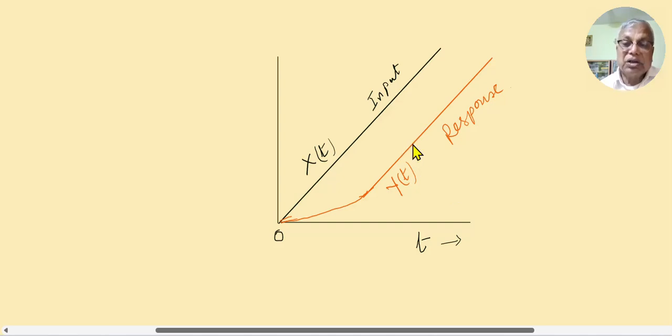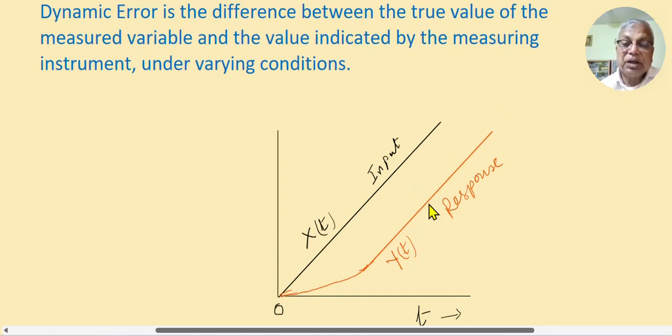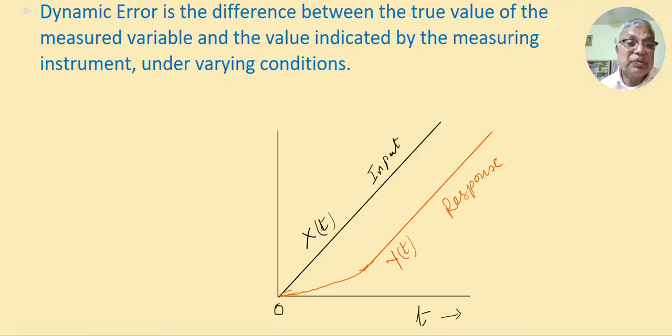And this graph will also show what is the dynamic error, the difference between the indicated temperature and bath temperature. If you take it after long enough time, you find out what is the vertical distance. Somewhere here. Read the value on the y-axis. This value on the y-axis will be the dynamic error.